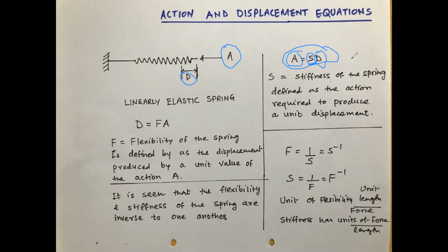There also we are bringing the concept of elasticity, because a spring is elastic and we are also assuming all structures are elastic. In your solid mechanics course, you have drawn the linear curve up to the elasticity limit. We are not going to the ultimate limit. We are going to analyze structures which behave linearly in force and deflection, stress and strain. The stress and strain curve is linear, so it is a linearly elastic material.